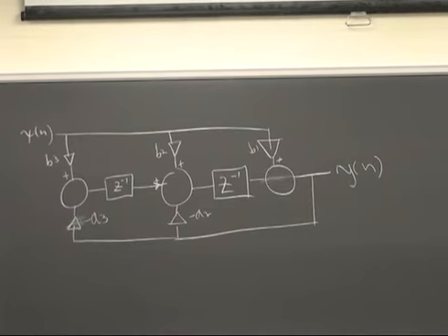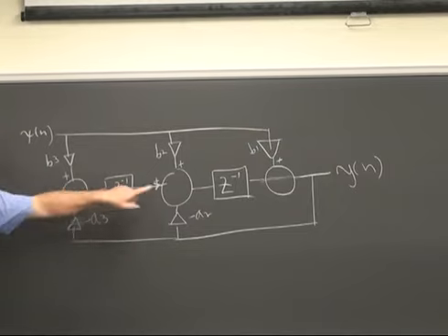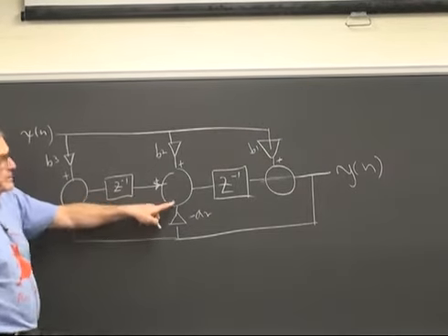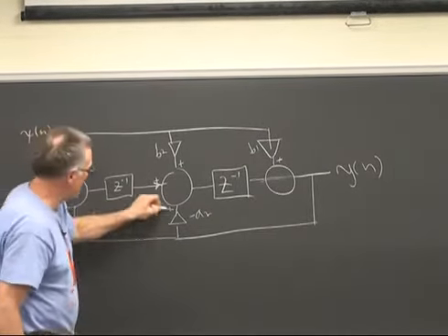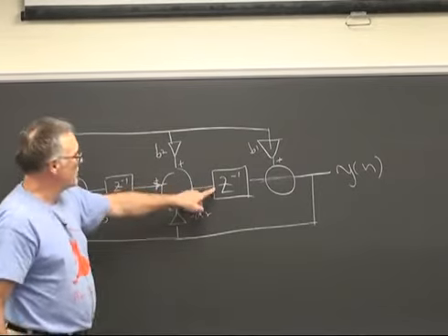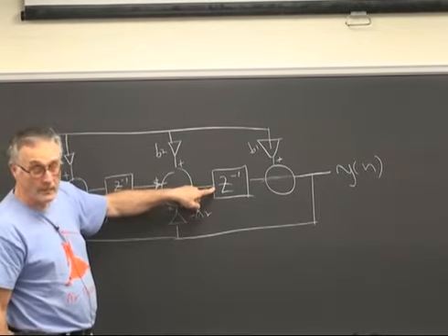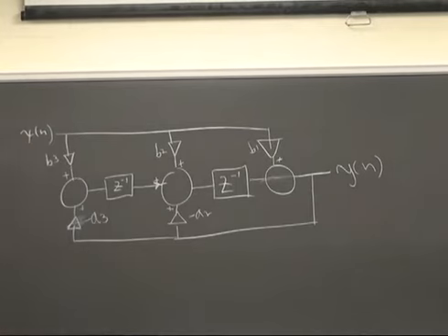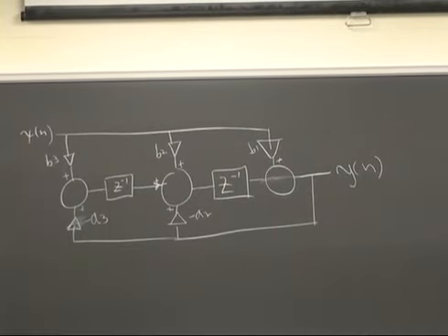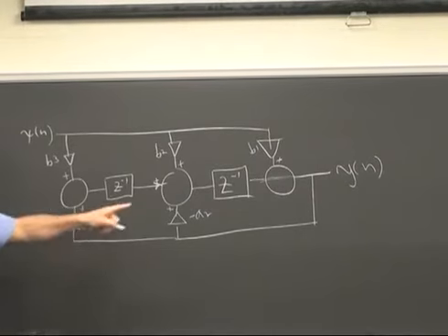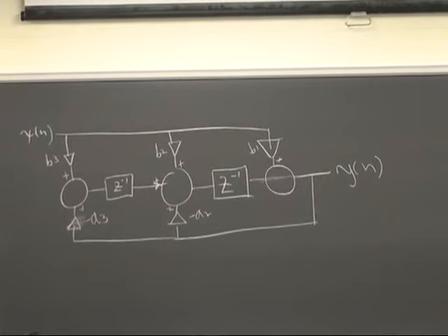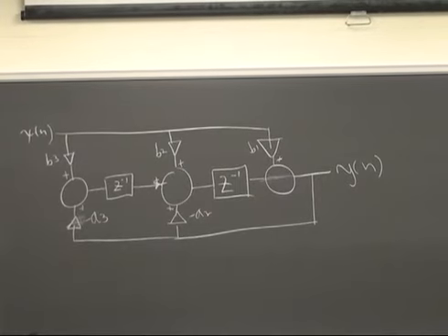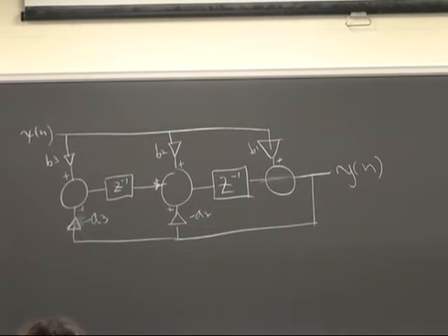One is it limits the add depth to one operation, or maybe two operations depending on how you think of it, per pipeline step. But you still have to do the multiply in the same cycle as the add, and it halves the number of pipeline registers necessary to implement this.